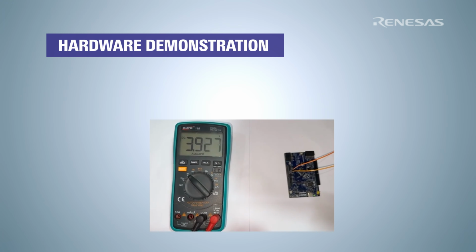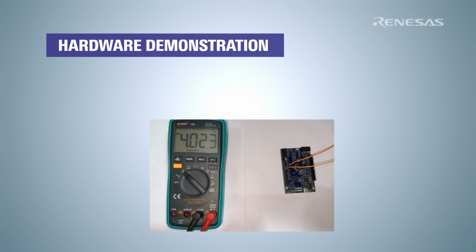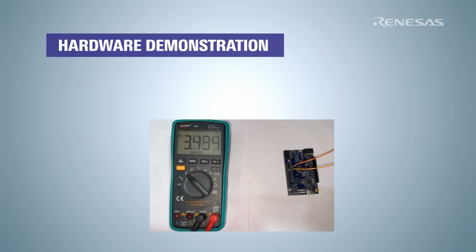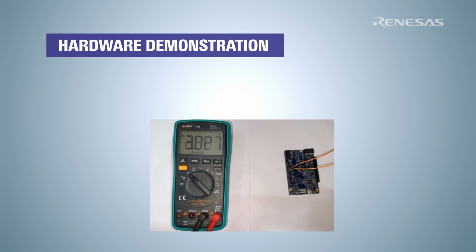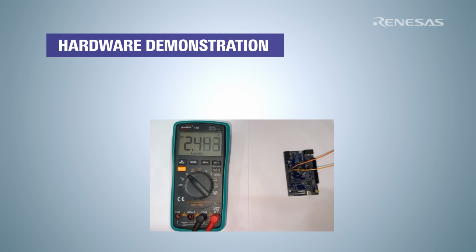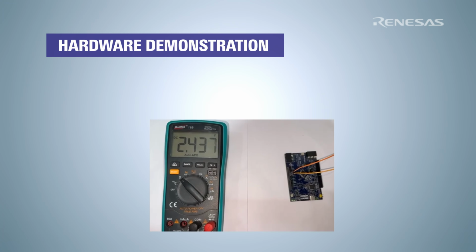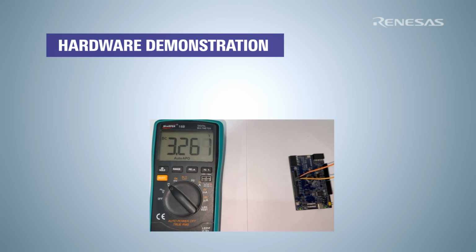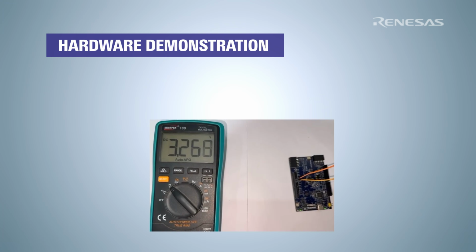Now I will slowly reduce the voltage. As you can observe in the video, when the voltage falls below the 2.76 volt limit, both on-board LEDs will turn on. When I gradually increase the voltage, the LED status flag will be set, and in the while(1) loop we will turn on LED 2, as we can observe in this video.